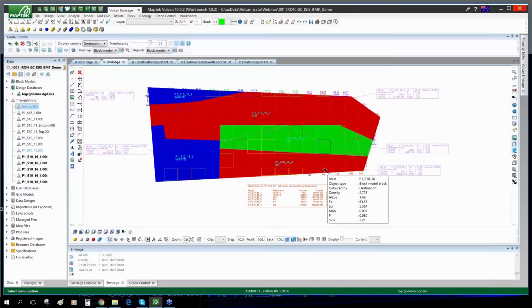So define different shapes and colors for your drill holes and samples. And one interesting thing is the scale option. That allows you to scale the size of the symbol to be larger or smaller to easily identify errors of high grade, for example, so you don't miss anything in the specific blast. So it's quite useful.